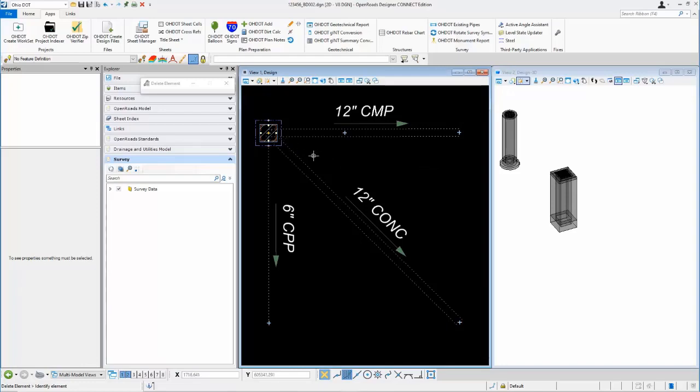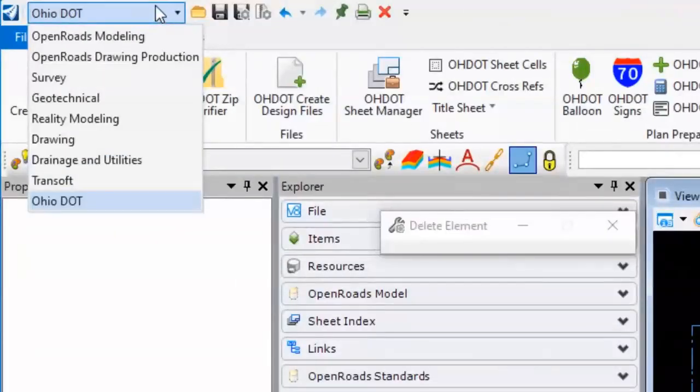So in order to put a pipe in, I need 2 nodes. So this structure that I've extracted is a node when we did our extract graphics for that. And what I need is a node to connect to. So I could connect a pipe between these 2 structures since I have 2 nodes just by selecting those nodes and using the create conduit command.